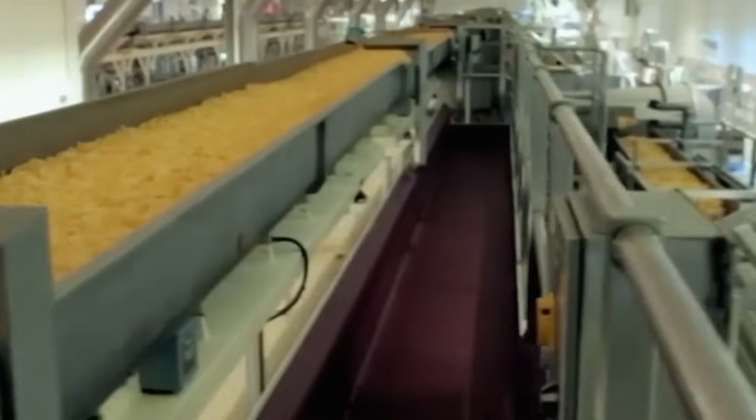Slices are carried through the fryer on a submersion belt that ensures each one is fully immersed for a specific dwell time, usually between 2 and 3 minutes. The exact time and temperature profile is controlled by SCADA systems to produce chips with consistent moisture content below 2%.